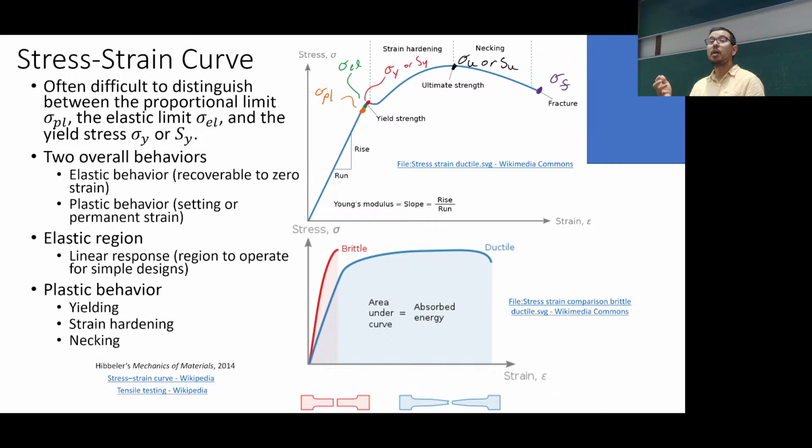The other thing is shot peening. People will purposely shoot little balls at the outer surface of structures to ding it, okay? By doing that, they've introduced plasticity to just the outer surface, which makes it stronger, quite frankly, and more resistant to potential failure.